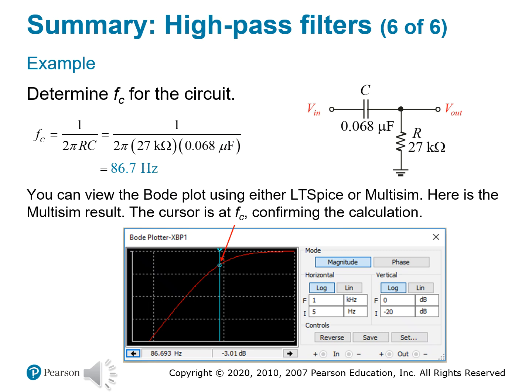The final takeaway here is that the filter behavior from both the math and the simulation perspective gives you a better understanding of the circuit. So whether you're going to prototype something like a guitar pedal or design wireless comms, the high pass filter, again, is the frequency gatekeeper. You can use tools like Multisim, and the author here uses LTspice as well. You don't need a lab bench to verify your designs. You can visualize performance with just a few keystrokes and a simulation. And that's it for this slide.